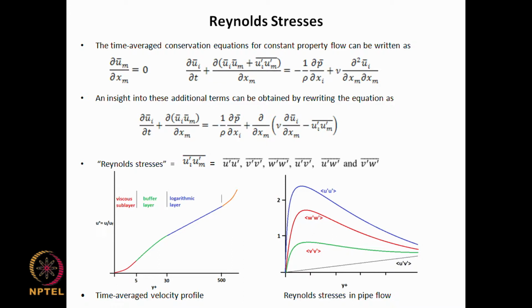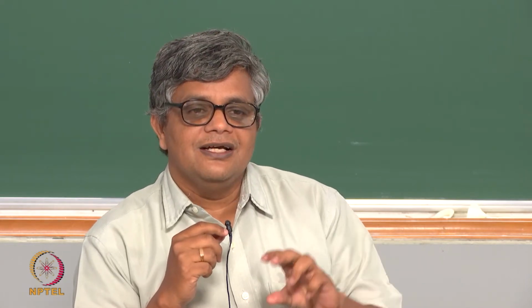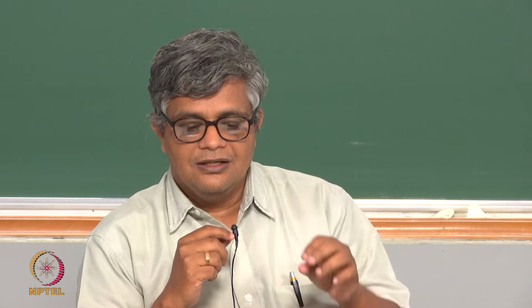We have seen that with a single scalar transport equation, it is relatively easy, but if you want to solve the Navier-Stokes equations, then we had to have special methods. Now you want to have k and epsilon as an extra set of equations. You have to solve for k, you have to solve for epsilon, and then you have to get the viscosity, put in the Reynolds stresses, put them back into the momentum equation, and resolve for all these things.